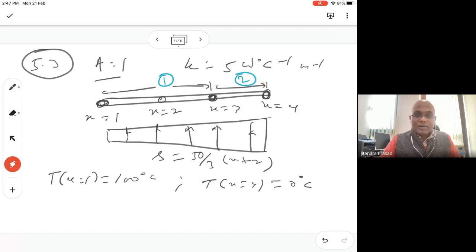What it asks is: first, write a strong form representing the heat flow and solve it analytically, finding the temperature and flux distribution. Second, construct the element source matrices and assemble them to obtain the global source matrix, noting that the boundary flux matrix is 0.